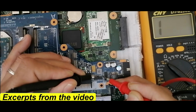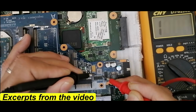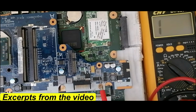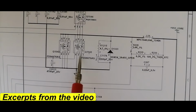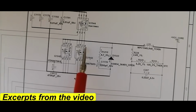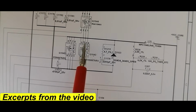The 3rd one, we get continuity. The 4th one, nothing, we didn't get continuity because this is the gate. So these 3 pins are connected together. This is the source, exactly as we have in the schematic. The other 4 pins for drain should be connected together.